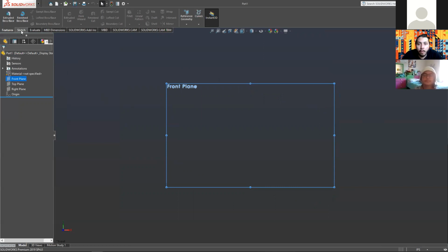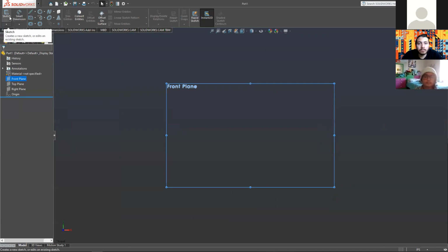Yes. All right. We can go to the sketch tab. Right now we're in the features tab. To the right of it is the sketch tab. We click on it, and in the top left is sketch. So we click on that, and now we're in sketch mode. As you can see, our little origin is highlighted with these 2 arrows. That's like 0, 0, 0 on our axes.